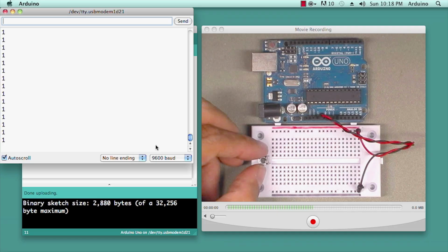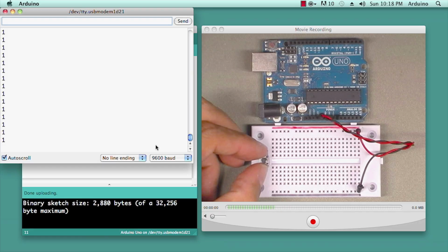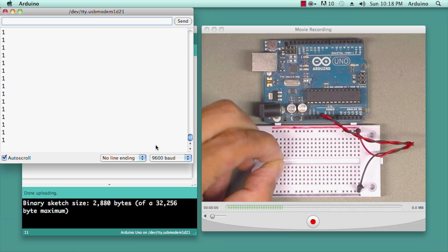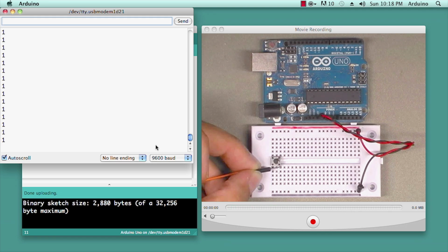We're going to put it above and below the trough, and notice that it's too short to go this way. So there's only one 90-degree orientation where it works and reaches across the trough, and that's the right one, of course, for it to work correctly. So I put it in, I plug it in like so. So the first thing to know, I'll use the wire as a pointer here, is that this point right here is now electrically connected to all these points directly below it in the column.